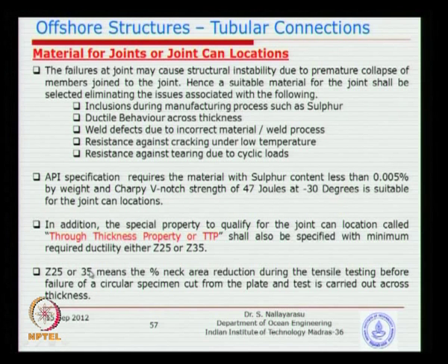And the notation here, basically Z35, Z25, is nothing but you take the specimen across the thickness and pull until the deformation is at least 35%. If it fails earlier than that, that means the material is not very good. So basically at the neck area you should get at least 35% extension.